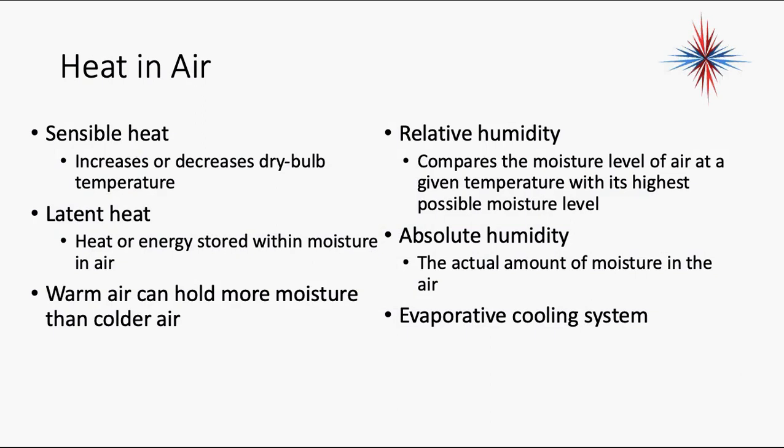Relative humidity compares the moisture level of air at a given temperature with its highest possible moisture level. Absolute humidity is the amount of moisture in the air. This all comes down to basically an evaporative cooling system. With evaporative cooling, all we're doing is using the latent energy.